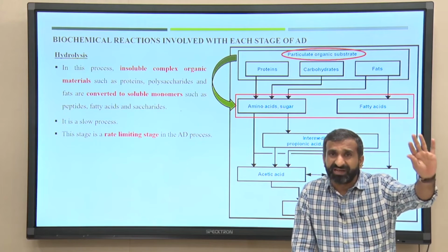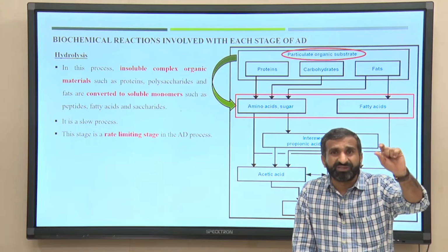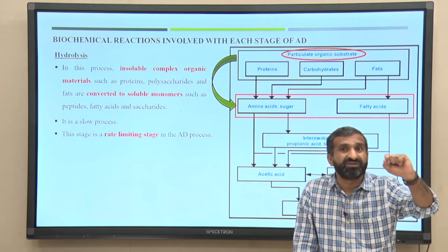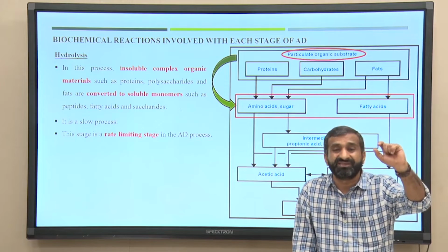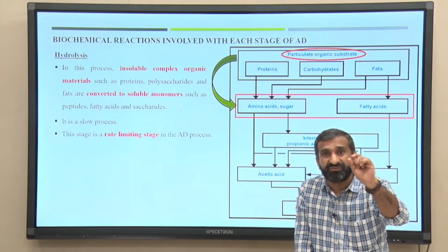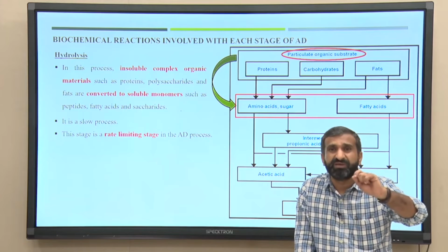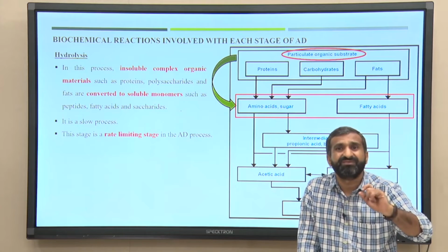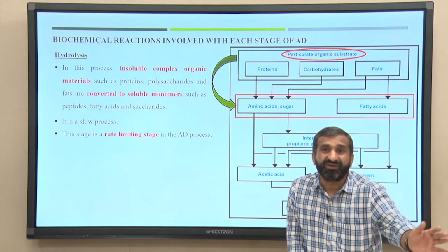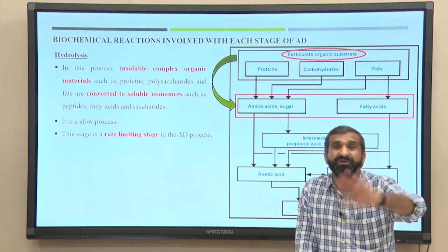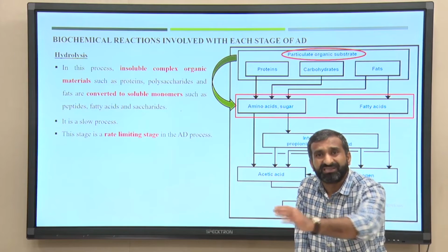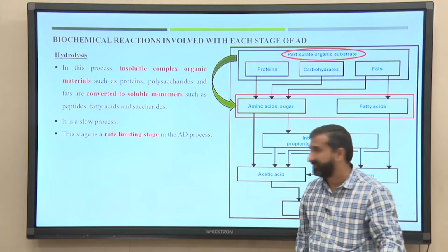Like in composting, I proposed a size of 1 or 2 centimeters is good for the bacterial degradation process. Here, reducing the size to 3 mm, 4 mm is highly beneficial for the anaerobic bacteria. So, mechanical grinding is one kind of hydrolysis or pre-treatment process, and the material goes directly to the acid forming stage.